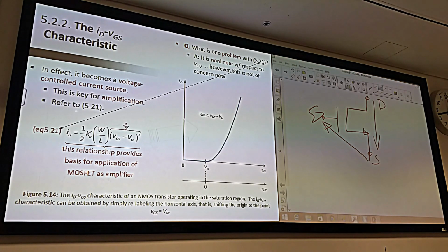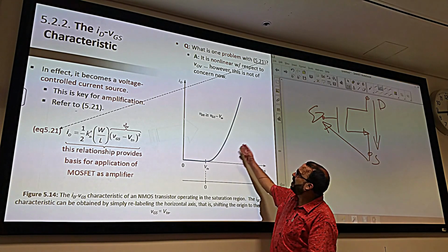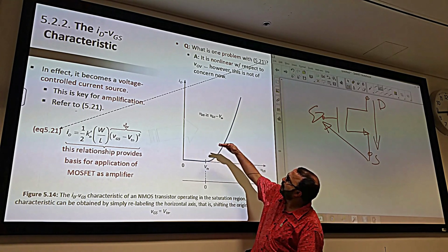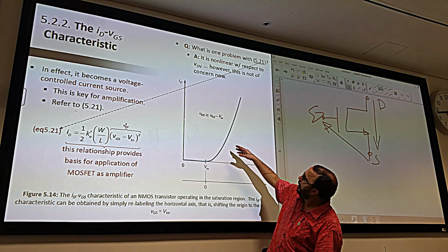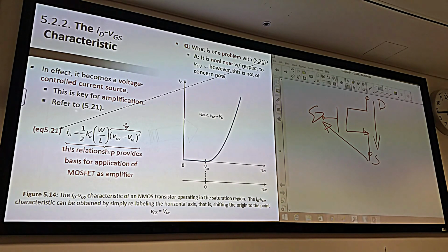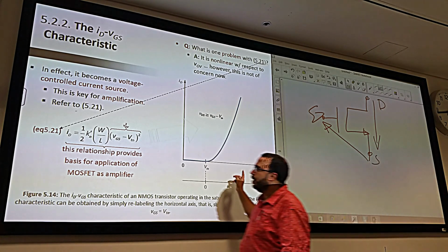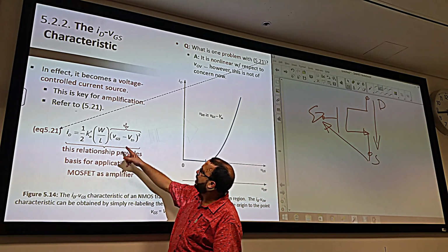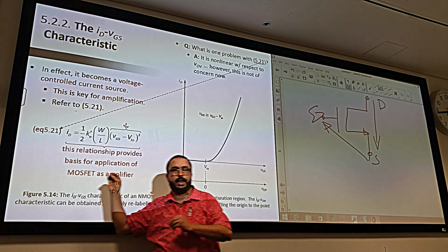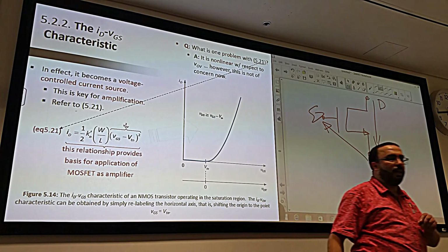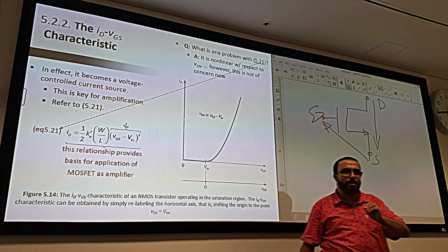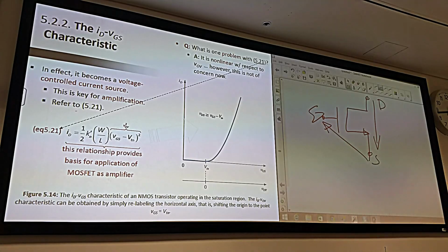Alright, good. So now we have a nice nonlinear equation. The input there, the output there. The output can go very high, very fast when this changes by a little bit, and that's the origin of the amplification. This will not happen if we are not in the saturation. That's the only place in the IV characteristic of the MOSFET when this happens. It doesn't happen in the triode.